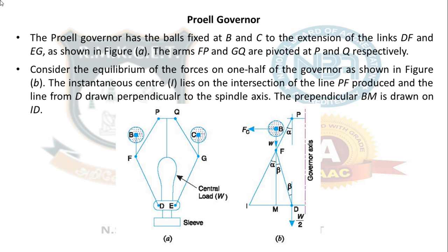The instantaneous center is located here. You remember the 4-bar chain mechanism. How did we locate the instantaneous center? Similarly, I am going to extend this link, and extend a horizontal line. They meet at the instantaneous center. I think this procedure you are very familiar with from the 4-bar mechanism. I am going to locate that neither fixed nor permanent instantaneous center, which is somewhere here.